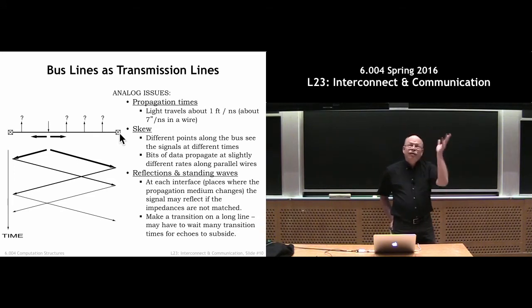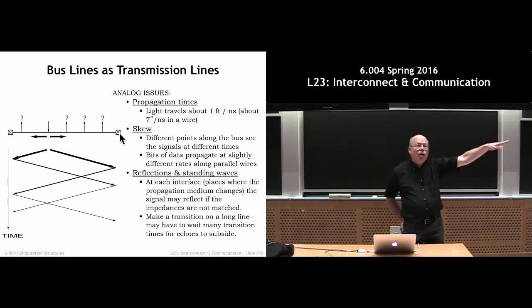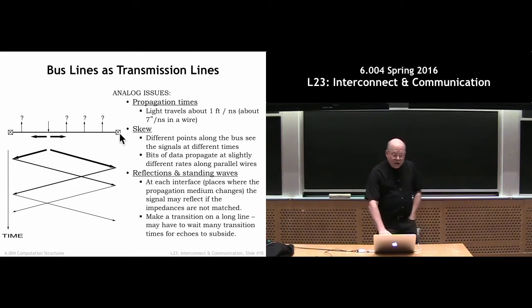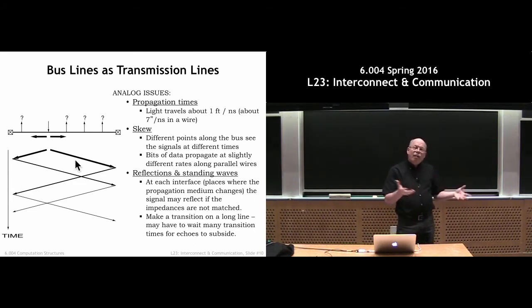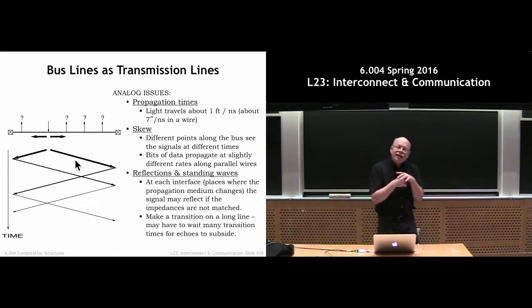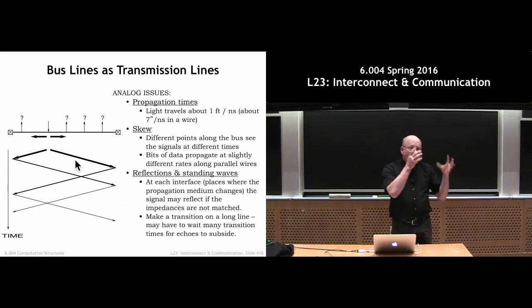Right, we're used to echoes, you can hear the echo in here. That's something that we expect. If I put energy that way, it bounces. It doesn't get absorbed by the wall. It just bounces back. And so, as it turns out, echoes from previous transmissions can complicate the reception of the current transmission. So it can actually get quite confusing. And a lot of communications engineering is spent dealing with so-called intersymbol interference, the notion that your transmission medium has a delayed response, an impulse response that causes some of the energy, some of the information from previous transmissions to corrupt the current one.